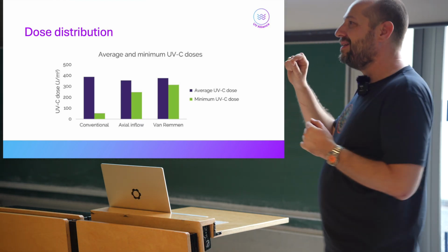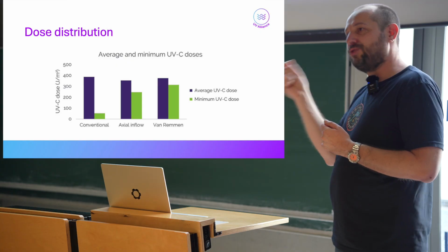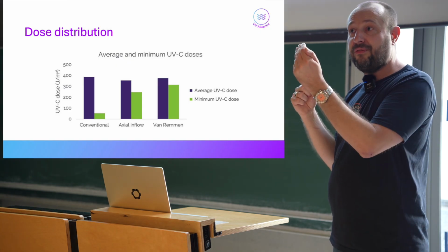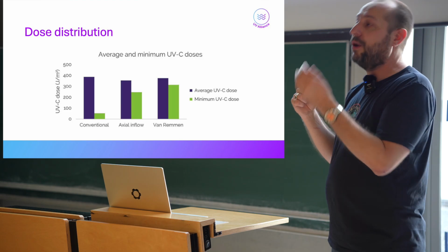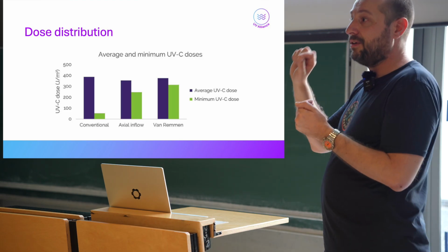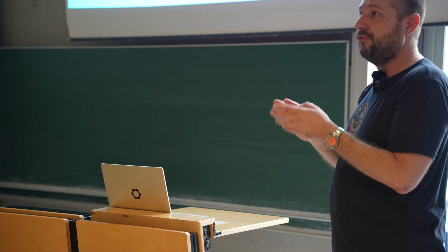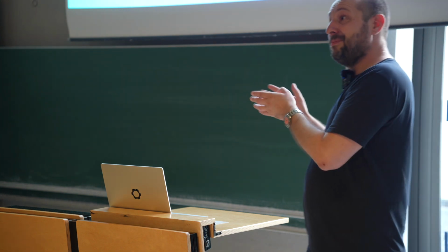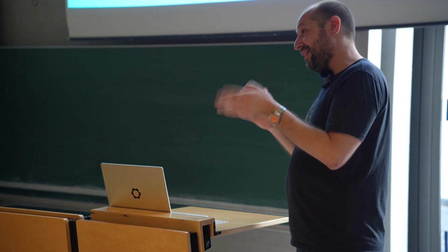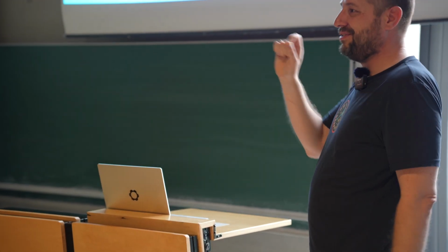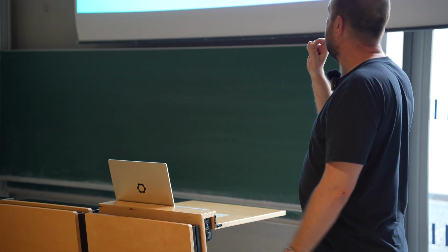This also means that every drop you're not treating well can make your system go from a log 5 reduction to a log 6 reduction or to a log 4 reduction. Because that last drop you don't treat contains enough bacteria to go from 99.99% reduction to 99.999% reduction. That last 1,000th of a percent is quite important.